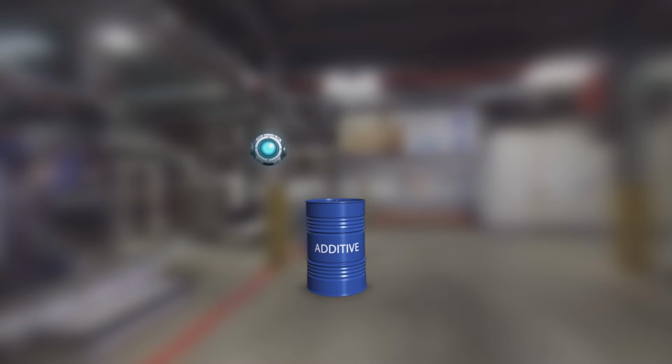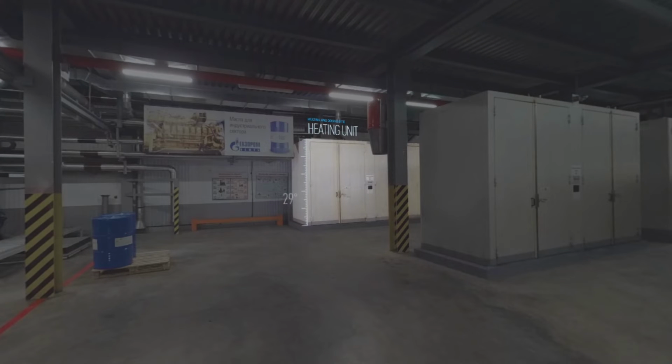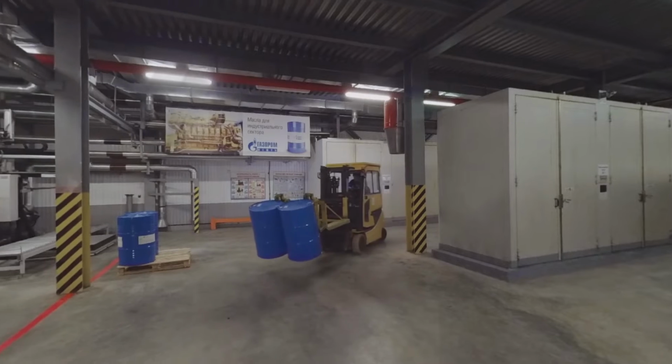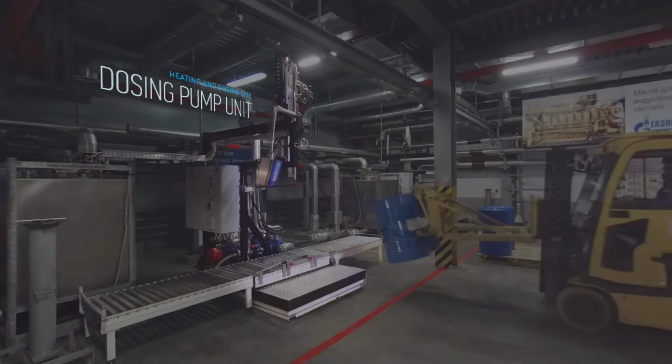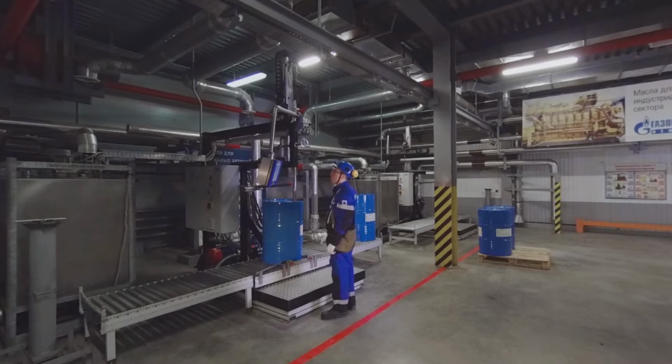Additives are transported from stock in a liquid form in 200-liter barrels to the dosage and heating unit, where they are heated up to the required temperature. After heating, the barrels are sent to the dosing pump unit. Dosing is as follows. The operator rolls up the barrel and starts the process. The sleeve is lowered into the throat of the barrel, and the predetermined volume of the additives is pumped through pipes to the premixing unit.